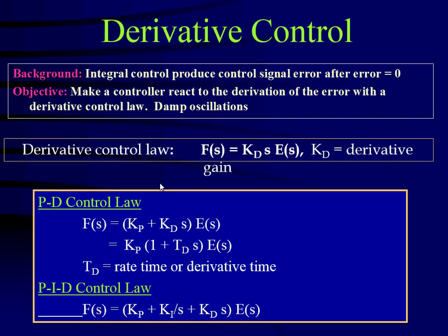So you begin to see that all three complement each other. Proportional control is fast. Integral control corrects the error, but if you put too much, the system oscillates. But it's like an antidote. To correct that, you put derivative control. Derivative control is damping in the system. So this one would actually introduce elements that dissipate energy.